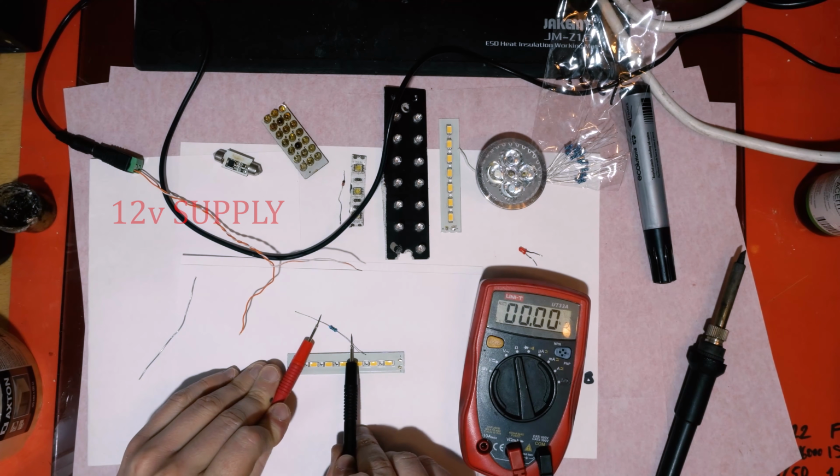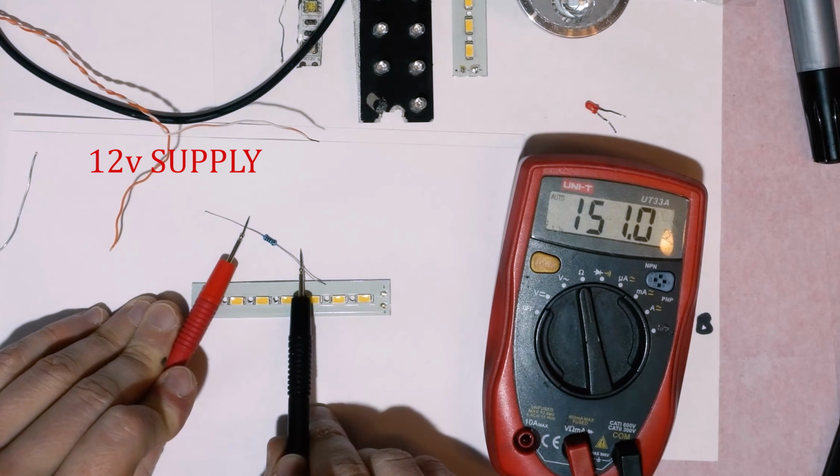I got this 12 volts power supply, but I decided to use a 150 ohms resistor, just to be on the safe side. As the current is inversely proportional to the resistance, larger resistor values produce lower currents. We do not know the actual working current value for this LED for sure, so we gotta take precautions.